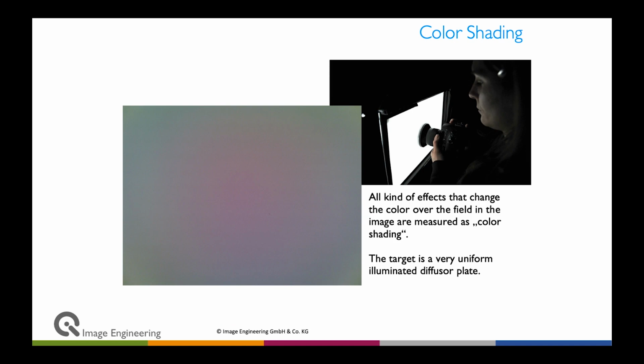needs to be done. And this particular color shading needs to be measured with different illuminants, because color shading depends on the illuminant. You have a different color shading when you use an A light source and when you use a D50 light source. That's where IQLED technology comes into play, because it can create these illuminants easily with the same light source. Both color shading and intensity shading, if you are in production line, are tested with a so-called flat field.